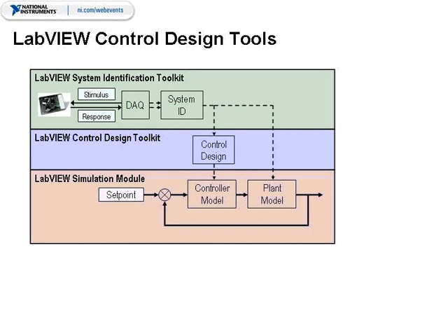This next slide shows these new LabVIEW tools and a different view on the interaction between system identification, control design, and simulation. As we'll see in a moment, the System Identification Toolkit provides the capabilities to use NI's data acquisition to stimulate the system that you want to control and measure the response coming back from that signal. With these I/O signals, System ID then can create a dynamic model of the system to characterize its dynamic response. This is the arrow coming out of these system identification algorithms up in the upper part of this slide.